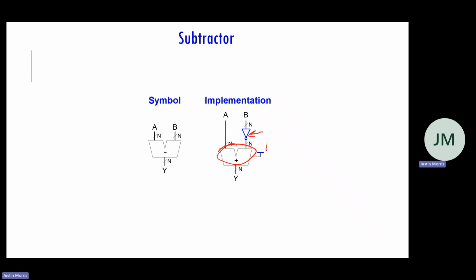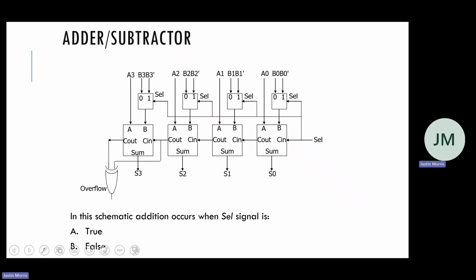And then if we don't want to make it a permanent change like this one is, right? Because this one, it's always flipping B. It's always negating, adding the carry 1. So it's always negating B, right? We can change it so that we can select if it's going to add or subtract.